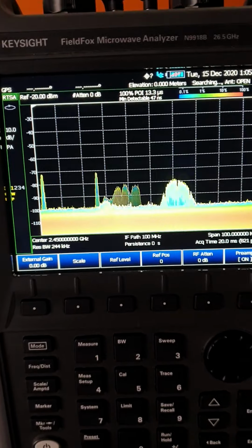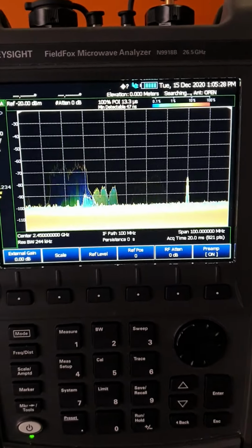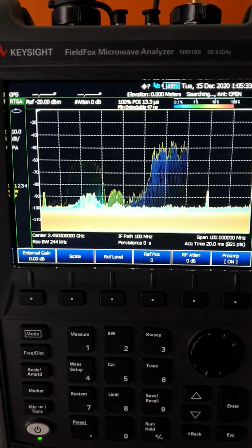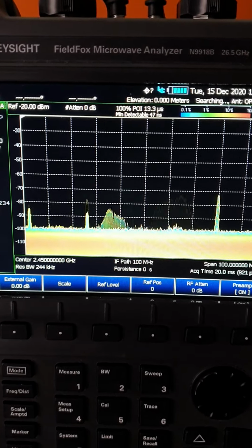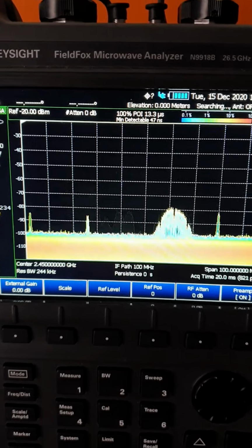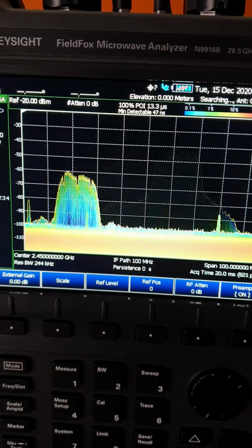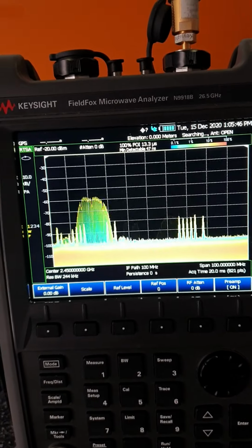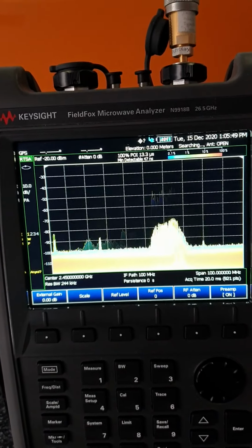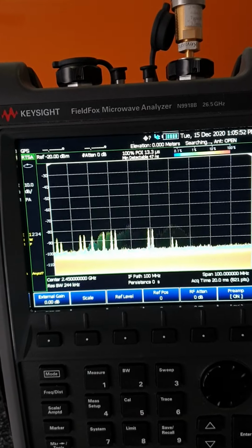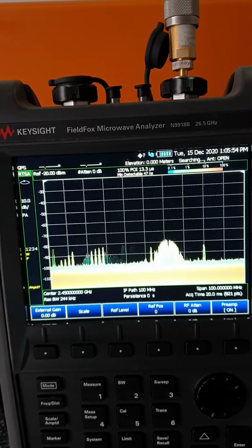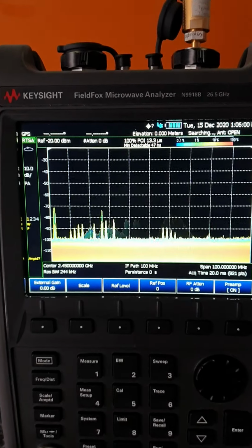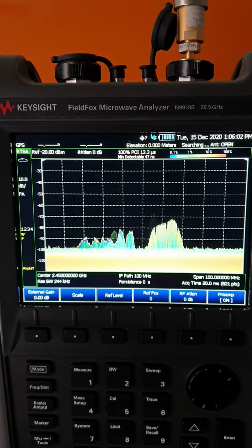So this should help you in terms of identifying the signals from your device, the signals from other things that may be around the area, and which ones may be causing interference with each other. This is what the spectrum typically looks like in these spaces, because these are generic, publicly available bands, and so you do have all of these signals sitting there at the same time, and reliance on the various pieces of equipment to be able to track and identify the signal that you are looking at, or the path you're looking at, rather than everything else.